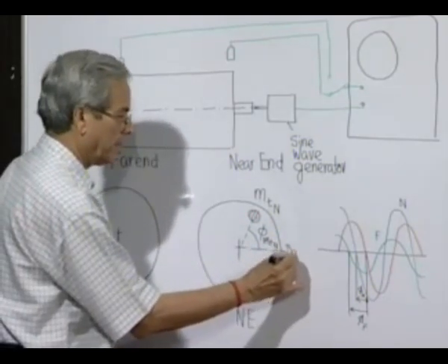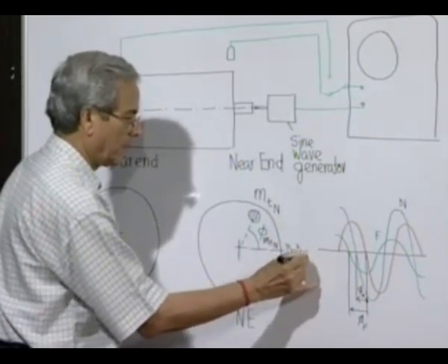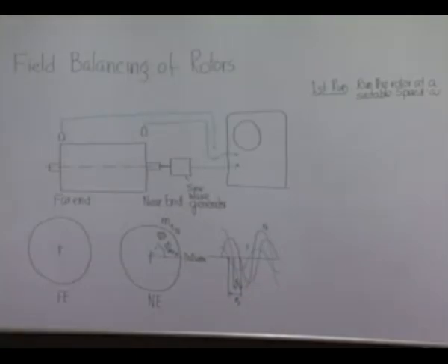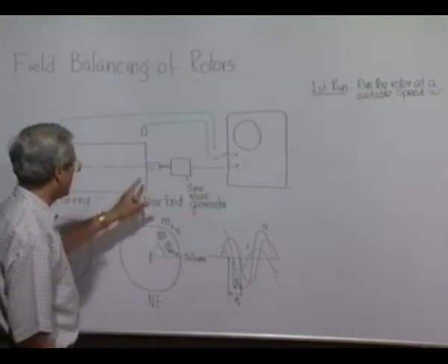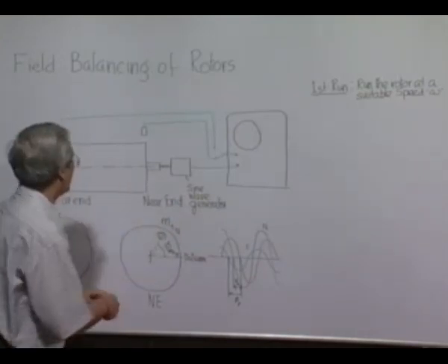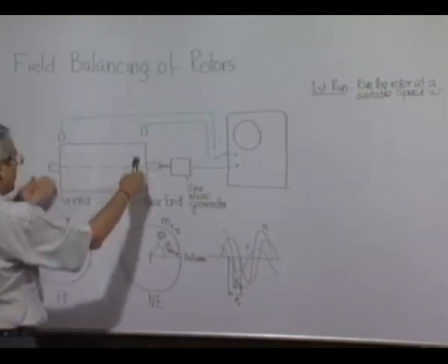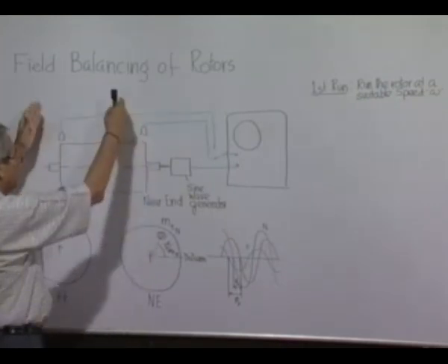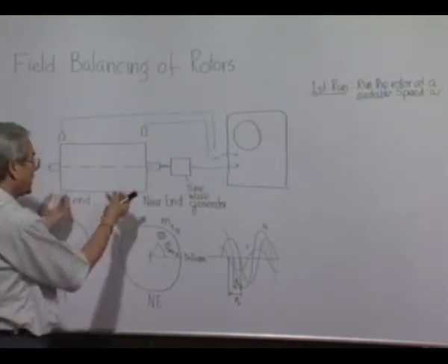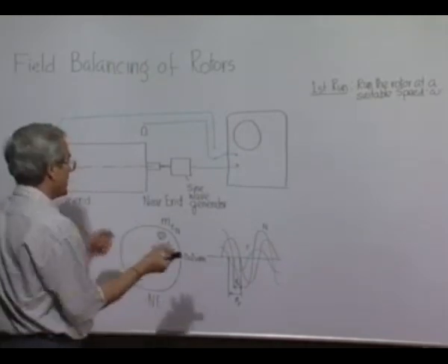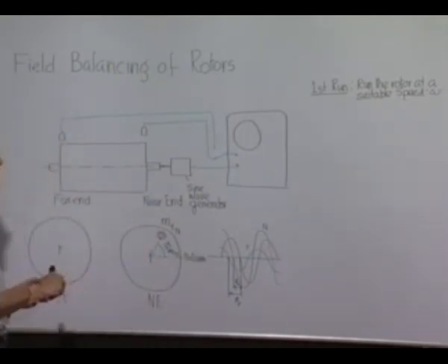This is a datum. When you do that, you have to keep in mind that these are also the chosen planes for putting balancing masses, or taking out material at the diametrically opposite location of the balancing mass, as I have said in the previous lecture.